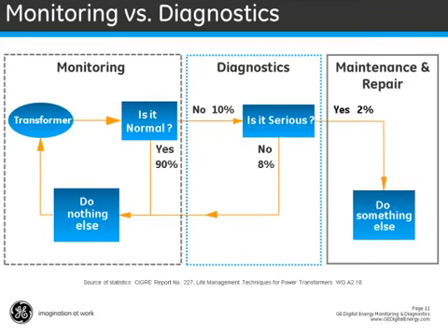Now, PCs located either directly on the transformer and in the substation or at a central server receive real-time inputs from the transformer and its components to not only record operational data, but to allow for complex calculations. These complex calculations provide the owner a very clear picture of the operating condition of the transformer, as well as enable the use of diagnostic routines to determine the health of the transformer and its components.